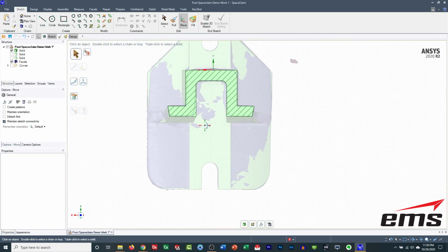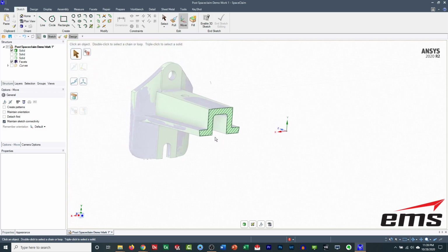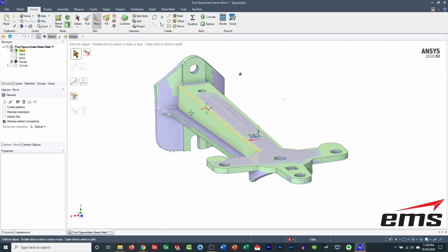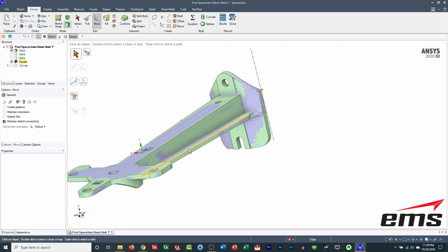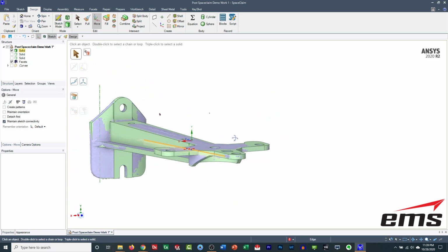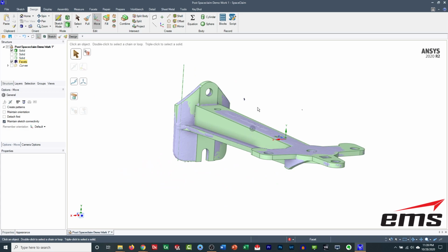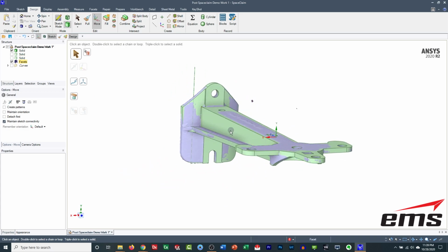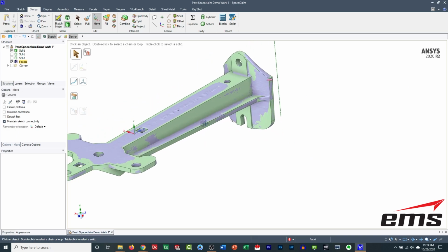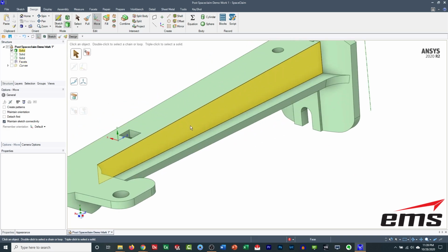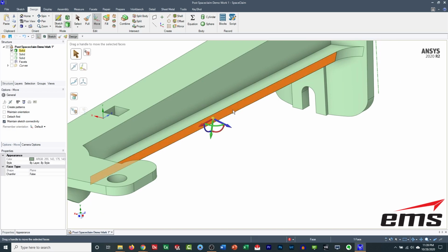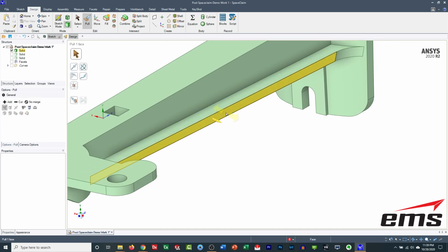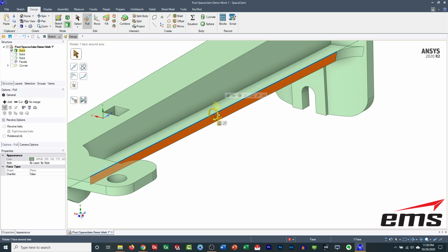So when we get done doing that, we're modeling here, as you see, in a 2D section. And then when we go back to our 3D view, it's updated that. So that entire feature now has that angle on it. So you can work in a 2D cross-section like we were doing with sketches, but actually do it on the solid body. Now, another way you can do the exact same thing is just in 3D with that pull tool. So we could have picked, let's go to the pull tool, that face, highlighted an angle, an axis, and rotated, also right there. So it's pretty cool.